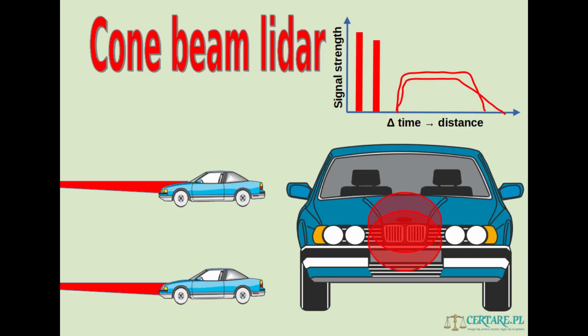And that, I think, is the first reason why they chose to use this cone beam that has a fairly large diameter, because when that beam is pointed at a vehicle and you read all the elements within that beam, rather than a single point from a very narrow beam, that allows averaging of each single distance measurement.